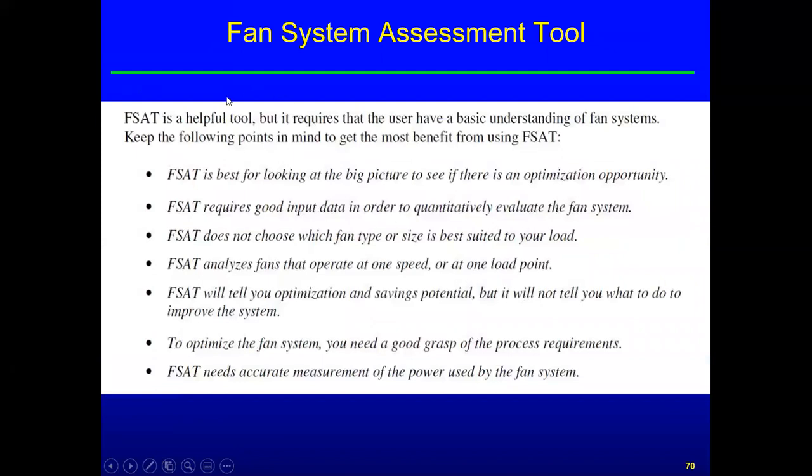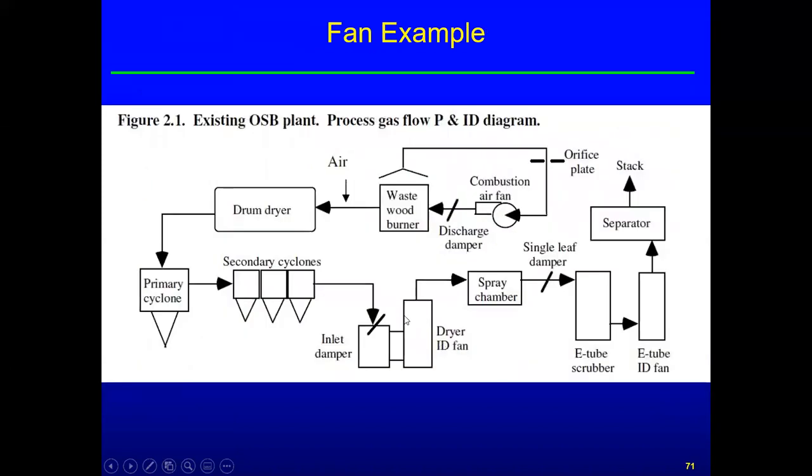And these are some other characteristics. This is out of an FSAT workshop I went to a long time ago. It just helps to quantify, see the big picture. It'll calculate the efficiency of your fan for you based on measurements. You go out in the field and take some data, come in and plug it in, that sort of thing. So we'll see that.